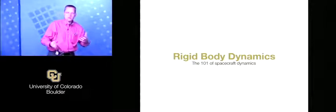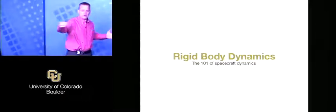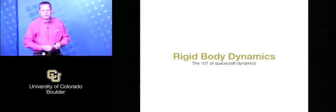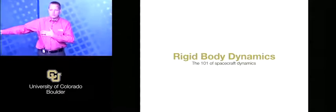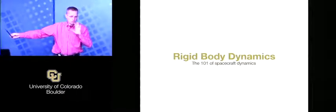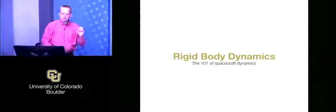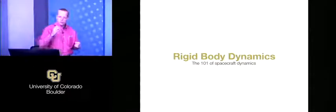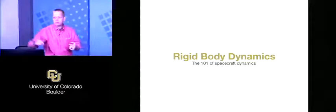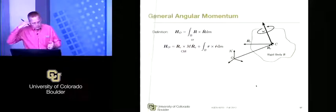So as we're freezing things, there was a question in the first lecture, why do we do body frame derivatives? Again, this is a case where it makes your life so much easier. You can do inertials, but then it's much more complicated in writing it out. In the body frame, if it's a rigid body, then the right wing should always be to your right, never to your left, or your plane has problems, right? They're no longer rigid. So that's the key assumption. R dot is going to be equal to the body frame derivative, which is 0, plus the transport theorem. That's the omega cross R. That's why it was omega cross R in there. That's basically how everything gets refined.